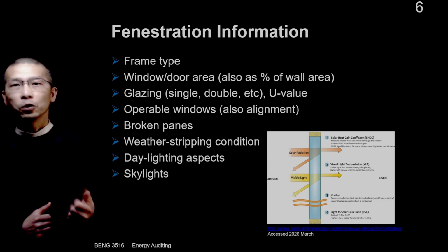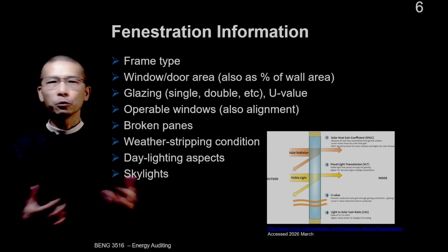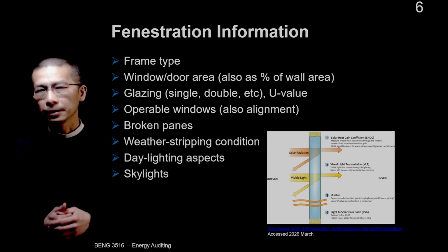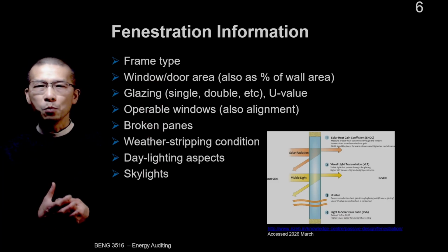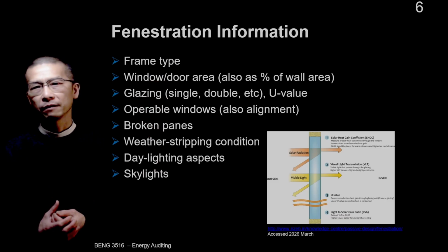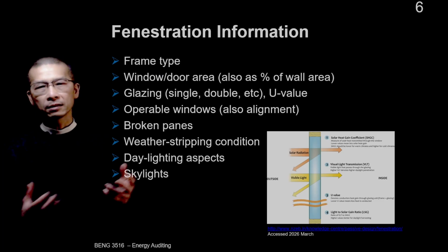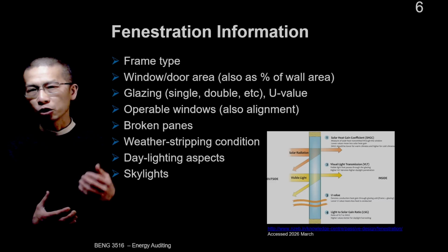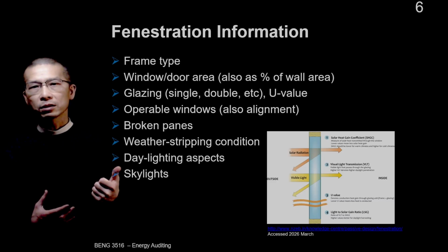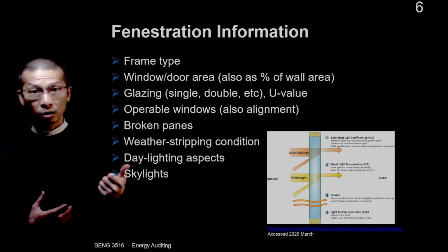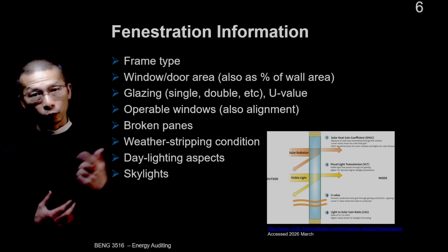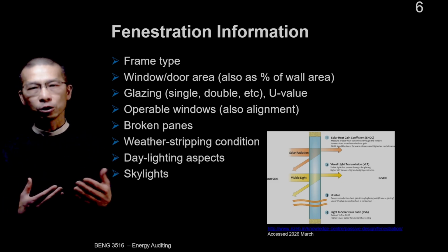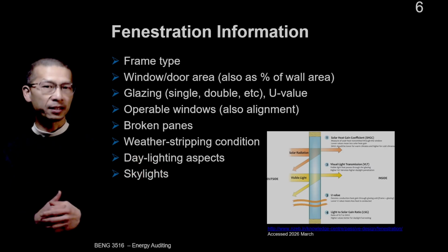Fenestrations, windows, doors. When we audit windows and doors, collectively known as fenestrations, we are looking at the most complex part of the building envelope. Unlike the solid walls, windows must manage heat conduction, that would be thermal conduction, solar radiation, and also air movement, air leakage, all simultaneously.